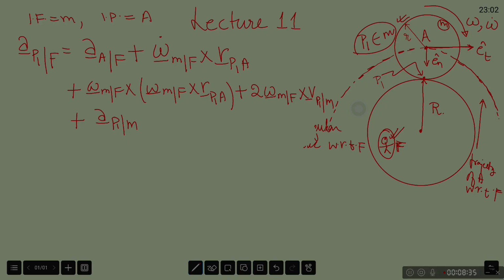As usual, having written the acceleration transfer relationship, I would like to sweep from right to left and mark the quantities which are known as K and mark the quantities which are unknown as U. And whenever I come across a new unknown quantity, I would like to write a new formulation so that I can find that unknown or can convert that unknown into a known quantity.